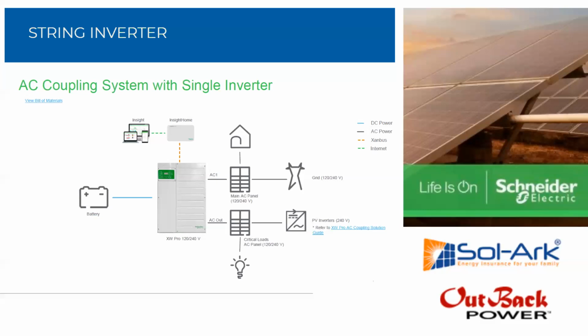And also to add this, Generac currently has the smart management modules for load control, but they're coming out with the Power Manager, which is also a main service panel extension, like an accessory, that pigtails onto the main panel in order to enable the automation for those loads. So keep your ears perked for load control equipment.